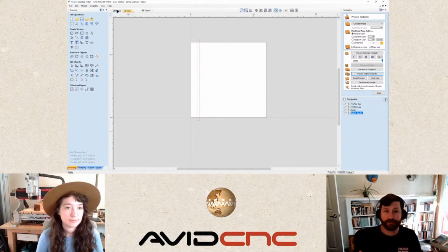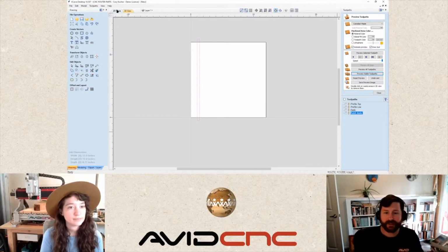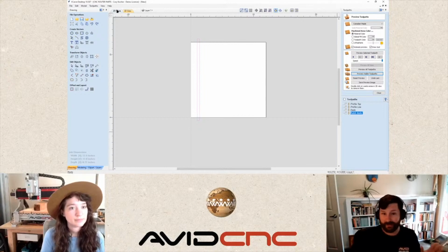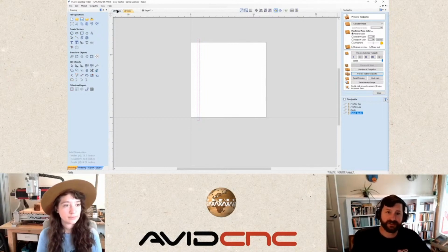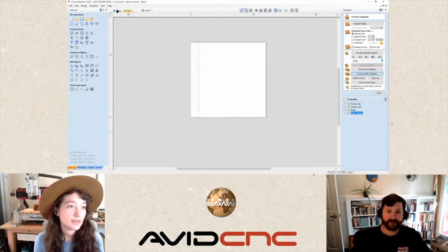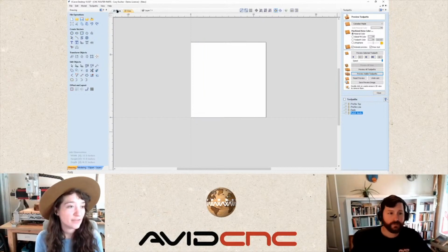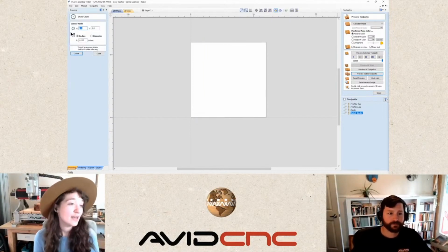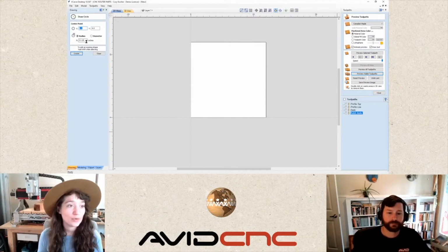With a typical drill bit or drill press, you're going to have RPM ranges somewhere between 200 and 1,000. I know that's a pretty big window, but it's typically going to be on the slower side of things, right, Sammy? Especially for drill bits, they're definitely going to be on the lower end versus what we have available with routers or spindles.